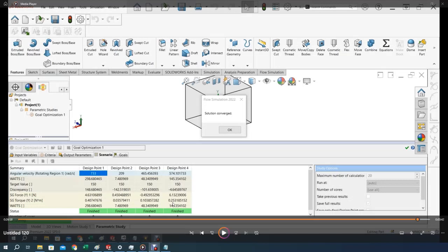So, thinking about it, what can be wrong here? Why is the force negative, because it should be positive. And you see the numbers here, how they look like something's not right, and I have to check on that. I think the problem is obviously not the optimization process. It could be the mesh might not be that good, but it could also be that it quit the iteration at a point that looked like it was okay, but it wasn't.